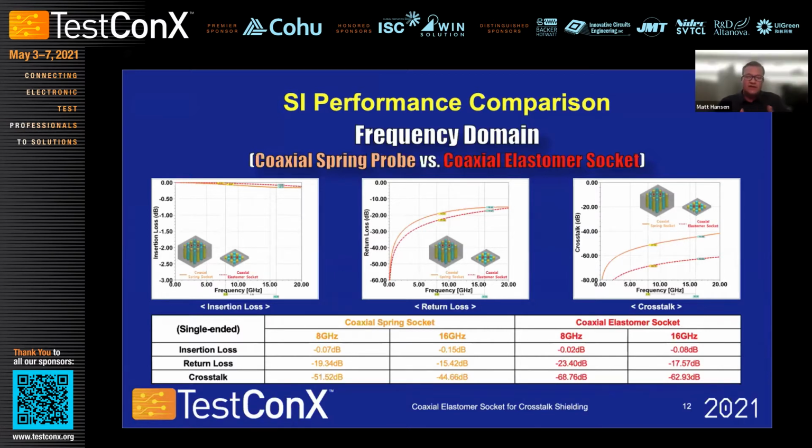Yeah, so my understanding is that the shorter signal path and lower inductance is the primary reason, and it probably also depends on any kind of stubbing you might have at the ends. So on the board side and on the device side, or the DUT side, you might sometimes, depending on how well you shield the ball and/or the spring probe.